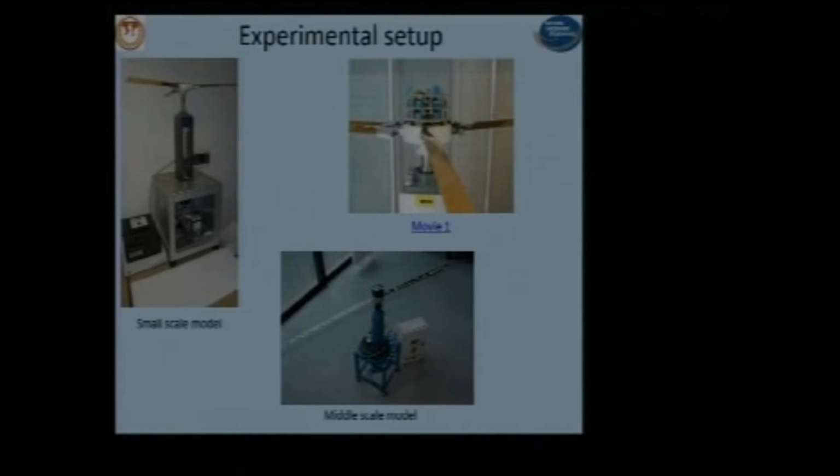You see the experimental part with some pointers. We want to measure vibration by using two high-speed cameras, and in this way we will detect this. Another problem included with this is active control of the vibration. You can see embedded active elements, PZT actuators, which are actuated by this amplifier and by the sliding rings. We can put voltage, and we can activate and control the behavior of this structure.